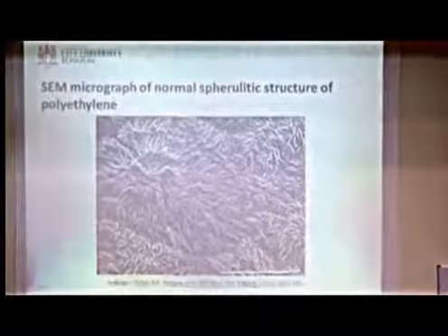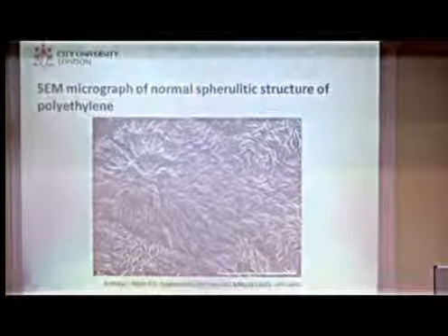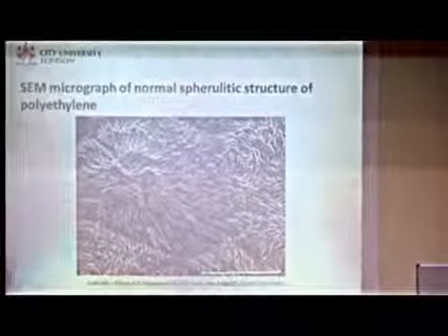It's quite well known that you can look at the spherulitic structure of polyethylene, and this one looks like a sort of Turner picture, or Van Gogh perhaps. What do you think it might be? A sort of close-up of a sunflower, I don't know. But it shows you all the structure that you can see in polyethylene. This is 10 microns across here. And so these are the lamella. You can see them sort of edge on there, being quite thin and stretching up for several microns across.